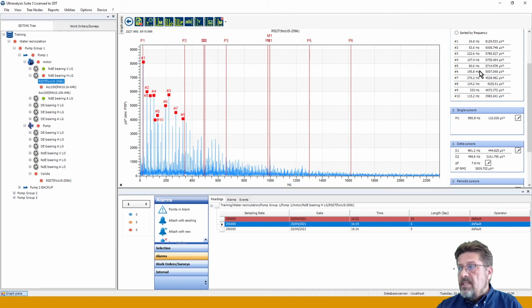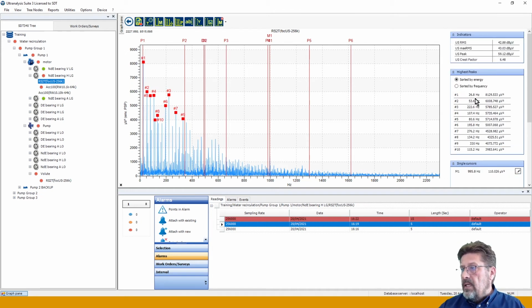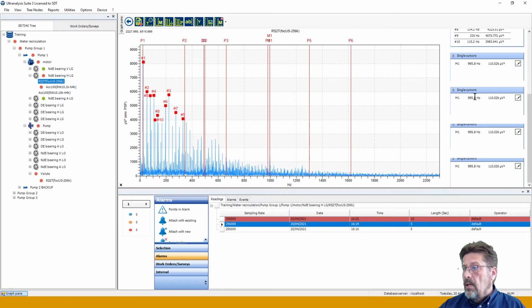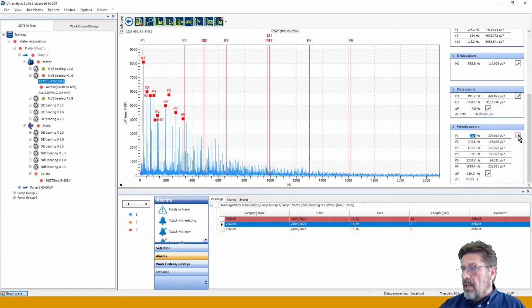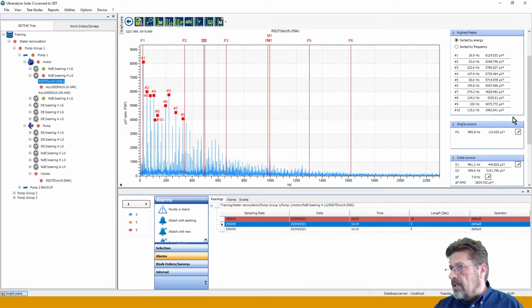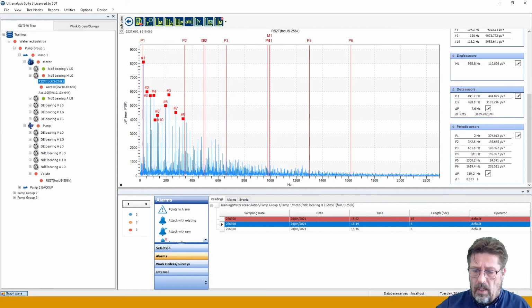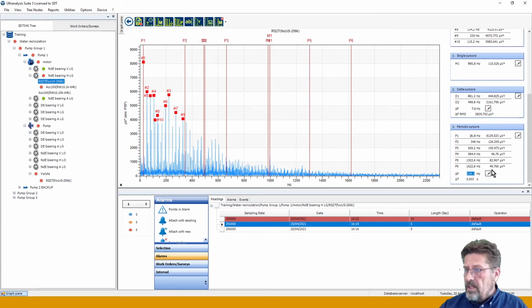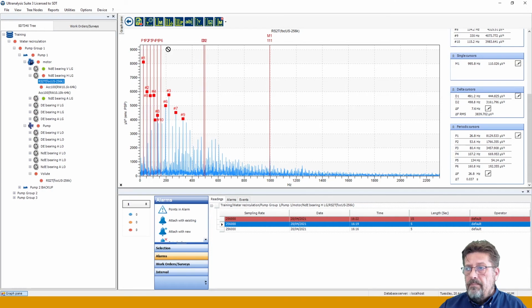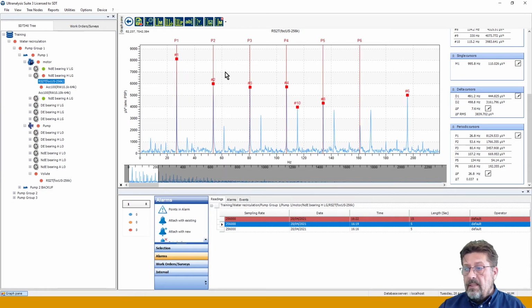To make your job easier, you can say, okay, my highest peak here is 26.8 Hertz. Good, so I will set my P1, and you can do it from here. You can set the position of P1 to, I'm forgetting fast, 26.8. So I will set it to 26.8, enter. Now it's completely aligned with 26.8. And I want you to set all the harmonics to 26.8. Let me see if they match. Oh, they match so nicely.